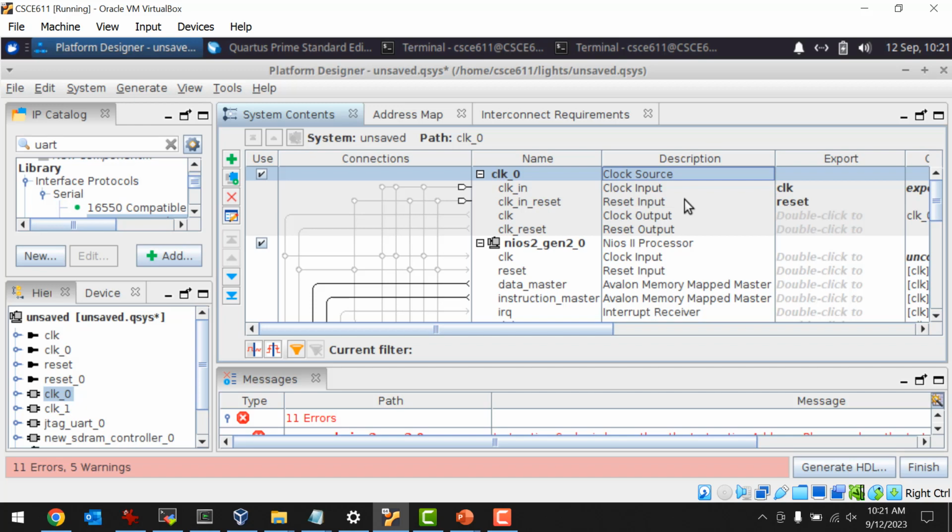The memory clock is slower because that clock goes out into the memory, and the wires that go to the memory from the CPU are long wires, and the longer the wires, the more capacitance and resistance they have, and the longer it takes to charge and discharge those wires, right? That's the RC constant, right? But on this board, they're the same because we're not being very aggressive with our clock speeds here.